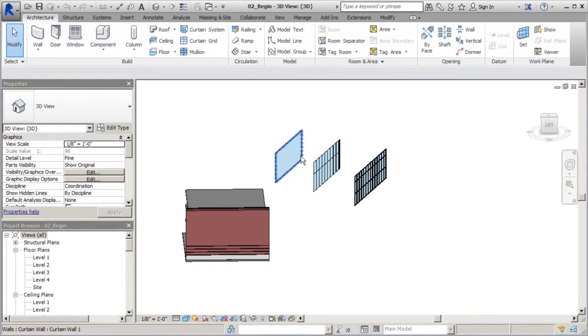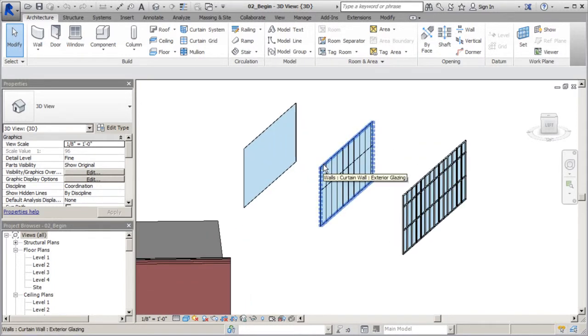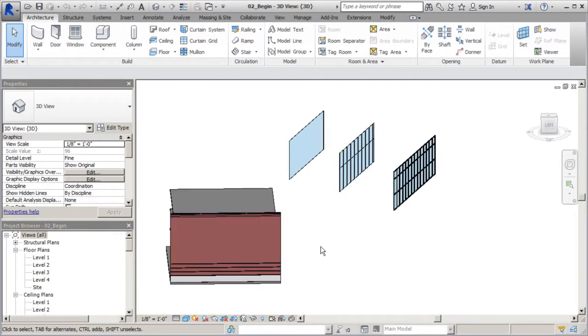Now that won't work necessarily initially when you're drawing these into a wall system, unless you go into the edit type, check that embed automatically, and then it'll behave just like a storefront system. But if you do not check that embed, this will actually be hidden inside the wall, and it could be a little bit challenging trying to figure things out. But we'll run into those issues a little bit later once we go over each one of these wall systems in detail.